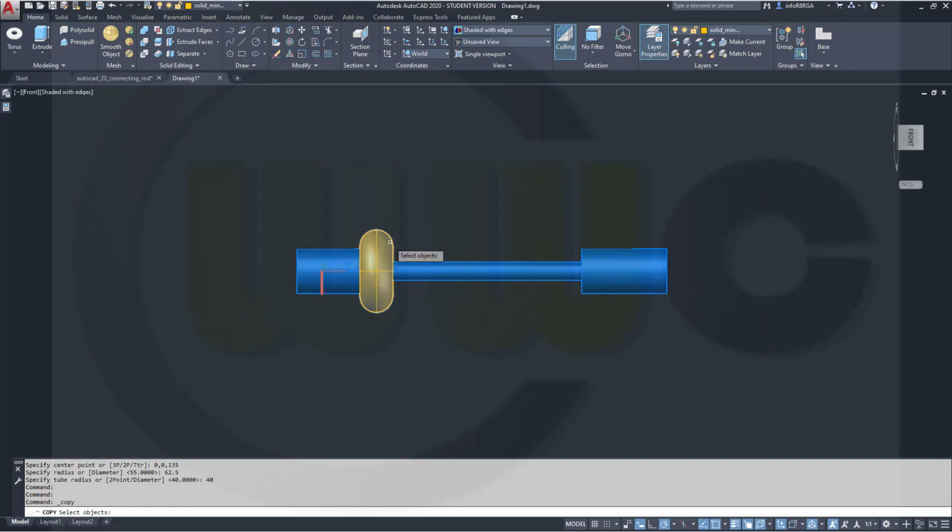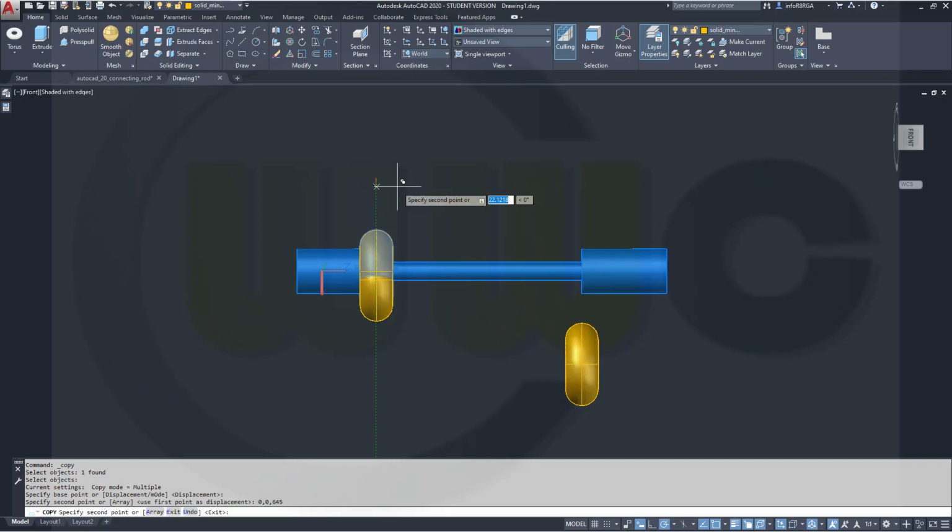Copy this one, right click, from some point to an absolute point, and that absolute point should be hashtag 0 colon 0, and then it's 750 minus 15, which is 645. No, it's 0 0 0 colon 645. Let's see. Not quite.